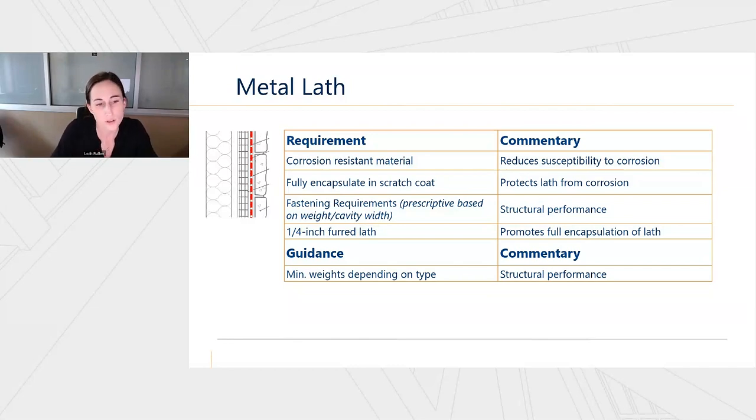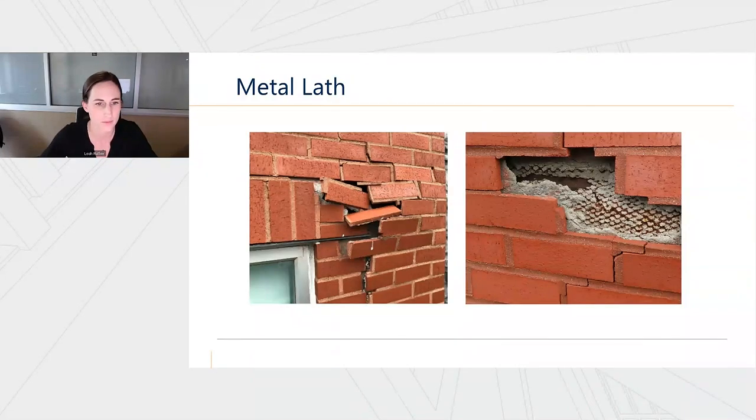There's also a requirement that the lath be furred, so a 1/4 inch furring. This does promote that encapsulation of the lath, and again, kind of reduces that susceptibility to corrosion. You can consider self-furring lath or other furring methods. And there's also some guidance regarding the different types of lath and various weight limits or requirements on size in different ASTM standards.